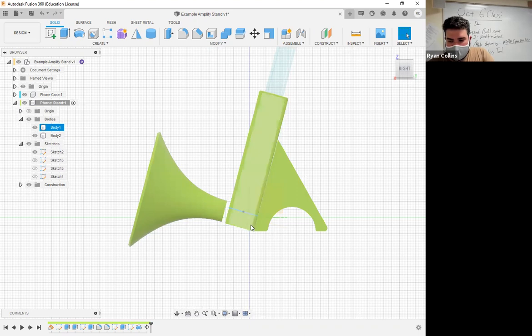And it really didn't adjust anything because I made use of a lot of parametric values as I snapped that bottom line just to that bottom edge. So it basically redrew some of my sketches for me. So this is why it is really helpful to make use of offset as opposed to redrawing a second line or referencing different things.